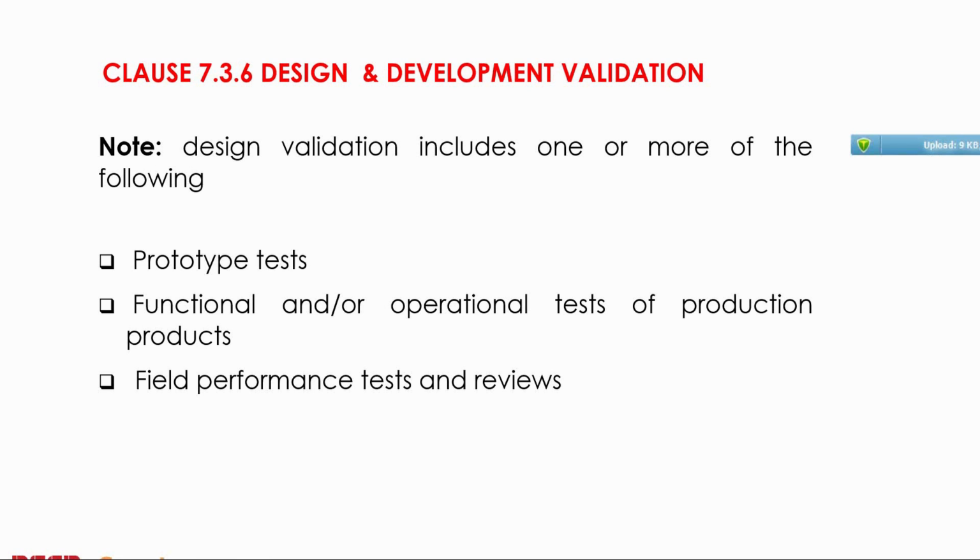Confusion often exists between verification and validation of designs. Verification is to check, whereas validation is to prove. Examples of calculations would be simulations or computer modeling to artificially test the design envelope. The output documentation must also be reviewed, not just the calculations. And the final part, comparing the new designs, they must be compared with other designs to look for any differences and similarities.